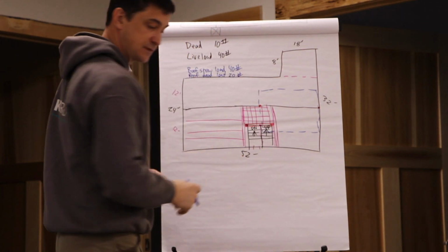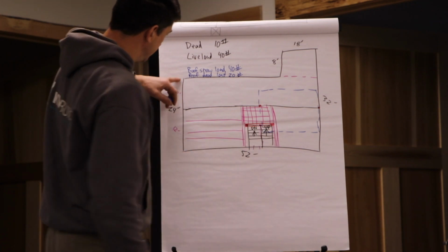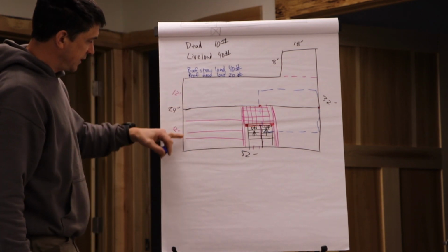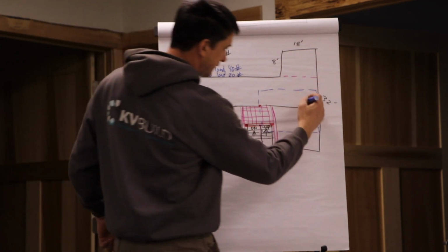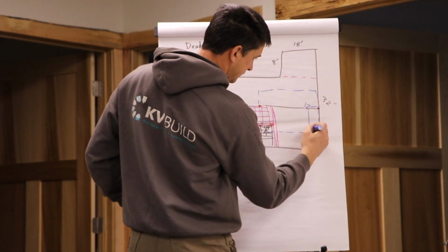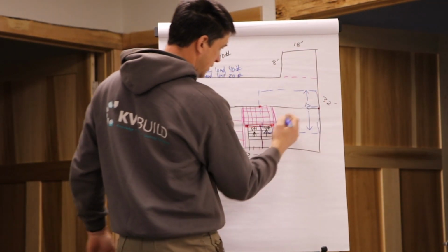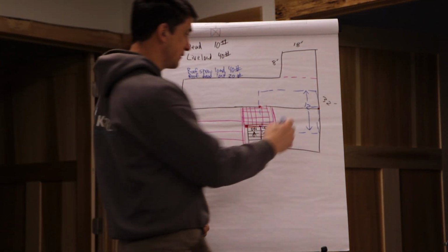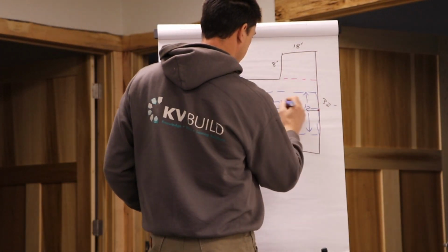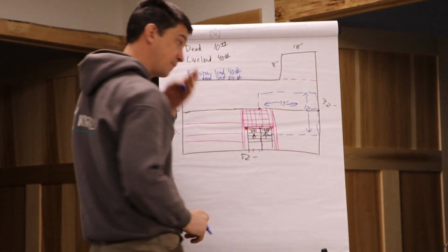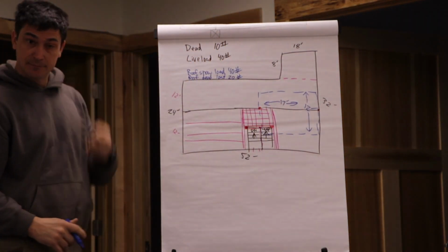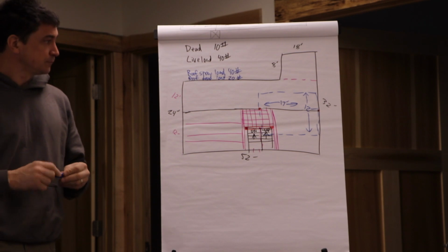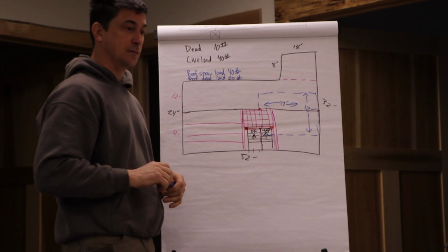Okay? So, this house is 24 feet wide. We've got half of that span, so we've got 12 feet, right? 12 feet this way we have to carry, and we're 16 foot 8, so let's say 17 feet this way. Okay? How many square feet is that? 204?